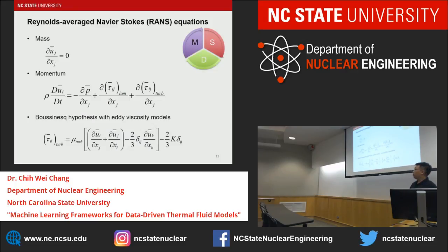First, we look at single-phase flow modeling. In single-phase flow modeling, we have the mass and momentum conservation equations. And usually, we need to use the Boussinesq hypothesis to approximate the Reynolds stress modeling. In the Reynolds stress model, the turbulence viscosity is a potential candidate to test the data-driven technique.